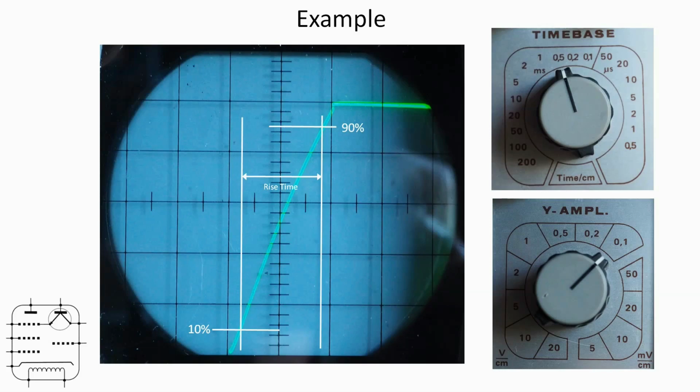Now by the miracle of computing, this animation was produced in PowerPoint, so I'm going to copy and paste that rise time arrow. There's an arrow which is exactly the same length, just pasted off on the screen there. And if I now add a 5 division per centimeter graticule there, we can see that that line is roughly, maybe ever so slightly less than 1.6 divisions. But for argument's sake, let's call it 1.6 divisions.